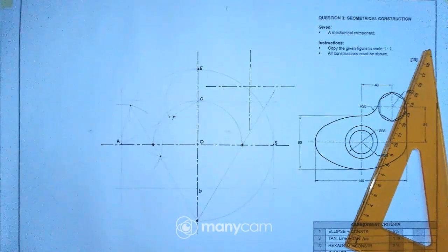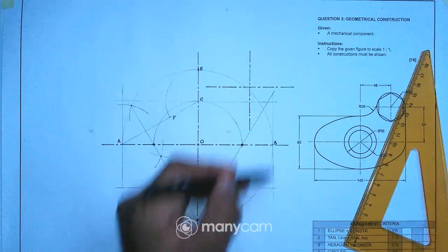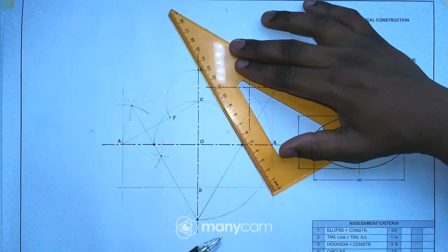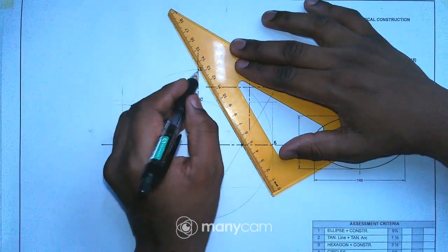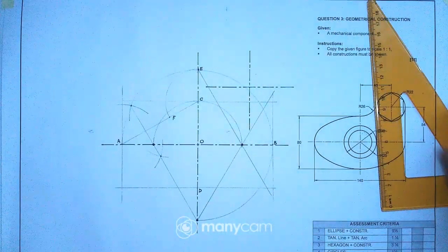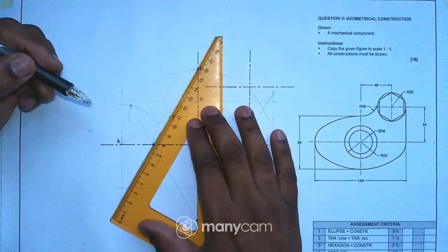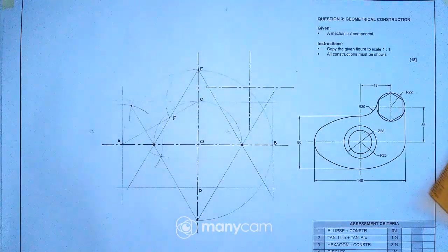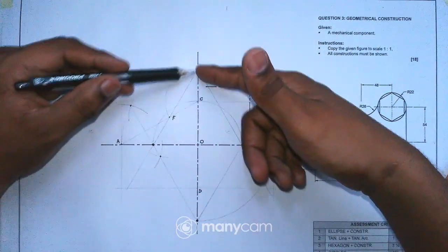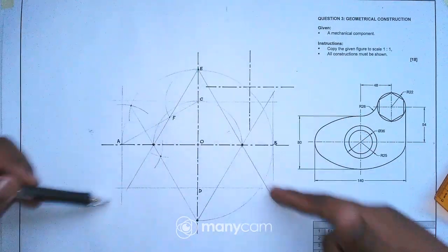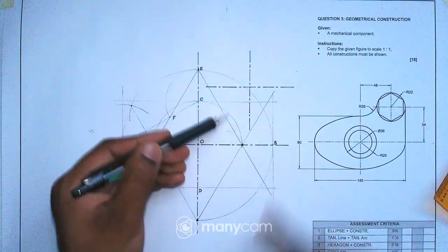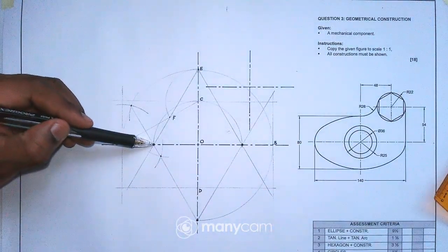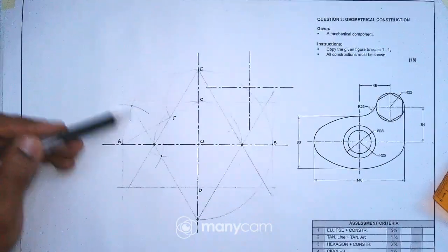Okay, it's fine. Therefore, after projecting this point up there, I can draw a line from that point across this point there, like that. And even this side, I'll do the same thing. Draw a straight line across that point. So as you can see, now I have the V facing down, but you must make sure that the V intersects with this line on the center line. Even this side, you must make sure that the line crosses this point here.